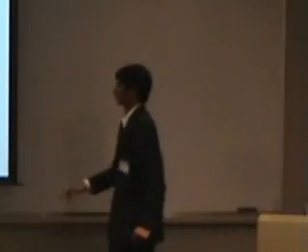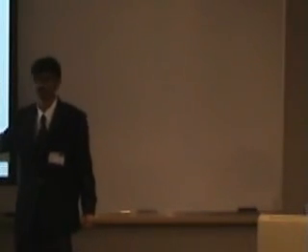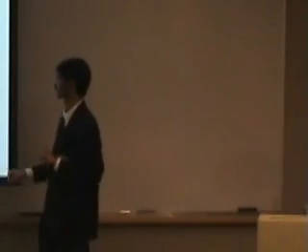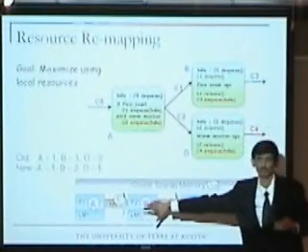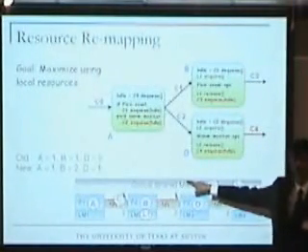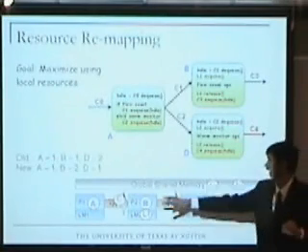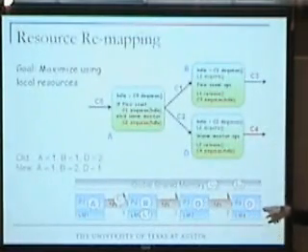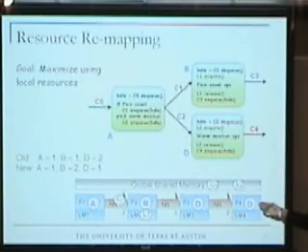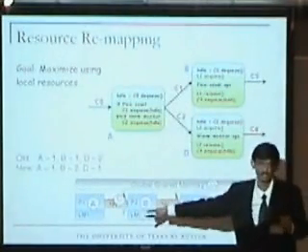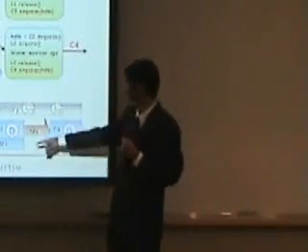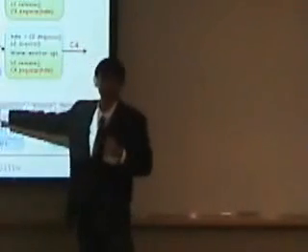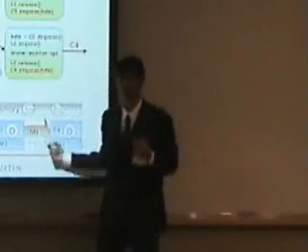So this resource remapping is not as simple as changing one D to B. This is where your question gets answered. Because A and B are communicating with a channel which is currently implemented on the next neighbor, we have to push it into the global memory so that A can communicate with B on 2 processors. And similarly, since D is working on only 1 processor, if I can move D to P2, then I can communicate using the next neighbor channel. Right. And the locks also. This lock has to be moved to the global memory, and this lock can go into the local memory.